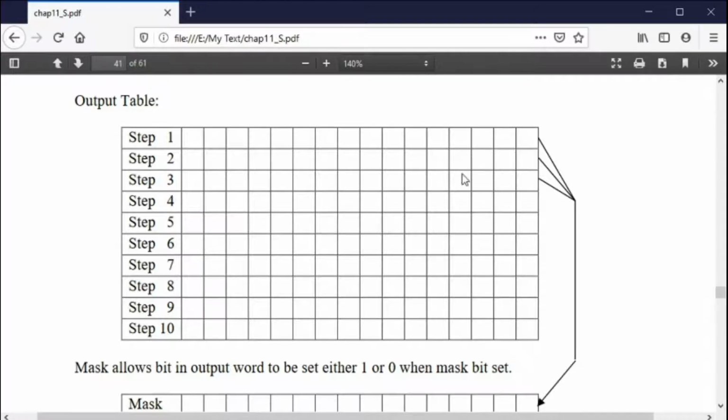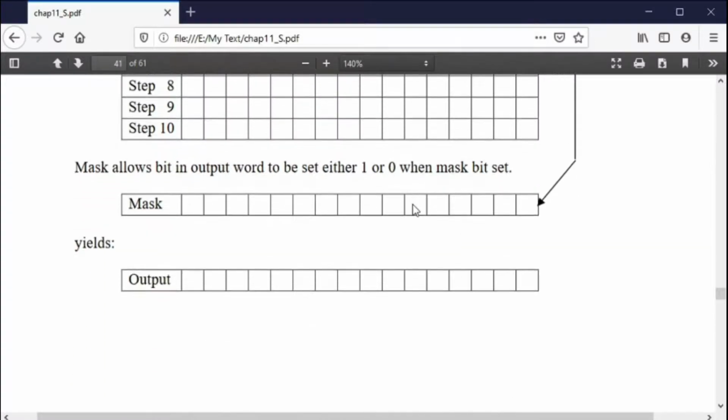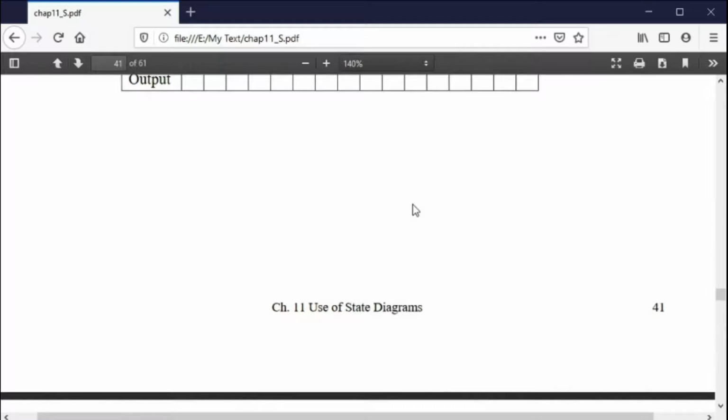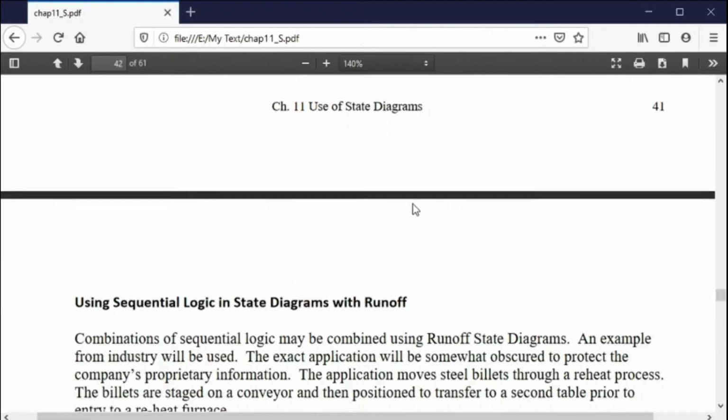So sequencer instructions, SQx instructions, are useful only if you have a large number of inputs and outputs, and if you have some documentation on it, or if you were the person that created it. It's useful in that situation, but otherwise use the steps using numbers. And that's my advice. Okay.